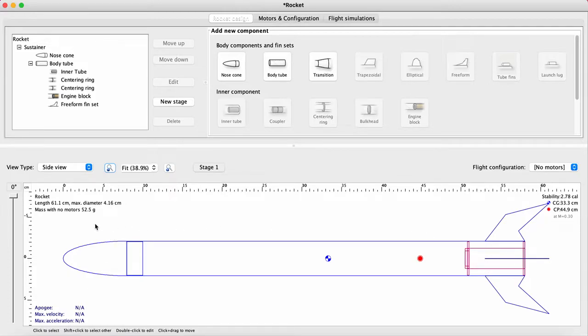You also have some drag up here at the nose cone, right? But if I was to average all the drag, all the force of all the drag over the total rocket, the average is about right here. Now here's the thing. This always has to be lower than or behind the center of gravity. If this ever exceeds and shows up over here, then you have an unstable rocket. Okay, and an unstable rocket is actually dangerous. You don't want this at the exhibition.